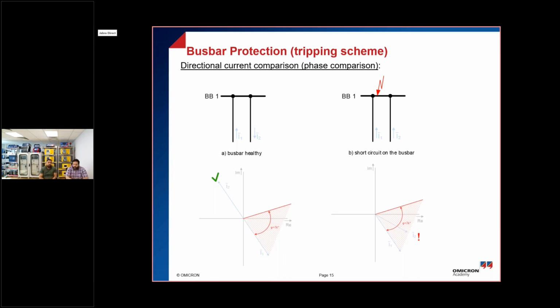Yes, exactly. It is, we can say, a backup way of measurement or a backup protection to avoid maloperation. As all of us know, whether I have an internal fault, external fault or a healthy condition, the current in should equal the current out. This is normal, even if the fault is outside the busbar. There is an external fault outside the busbar or a healthy condition, so you will see that both currents 1 and 2 are out of phase, because we assume that the current in is positive and the current out is negative. So if you would like to say -1 in electricity, it means 1 with angle 180. So 1 with angle 0 is 1, 1 with angle 180 is -1.